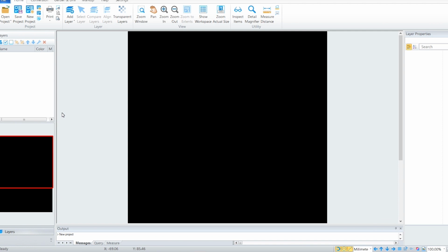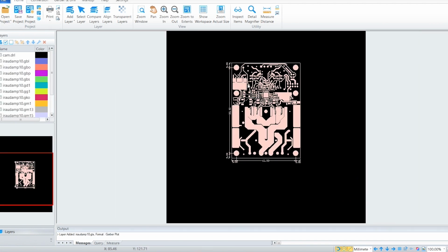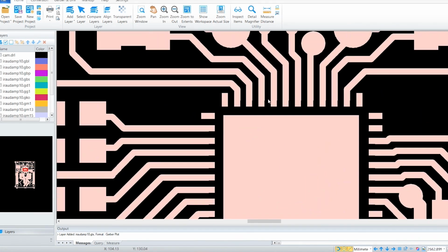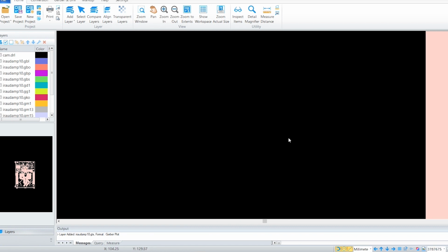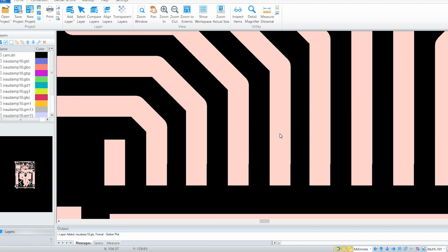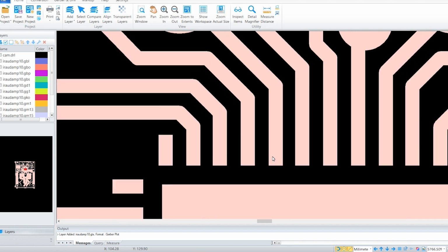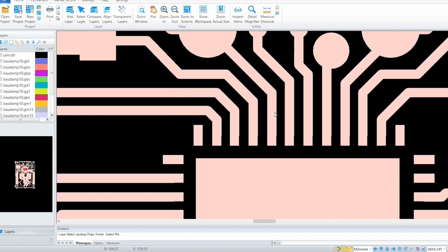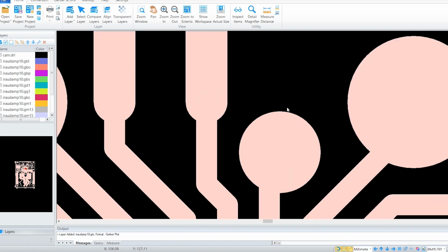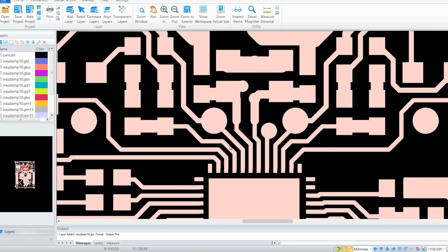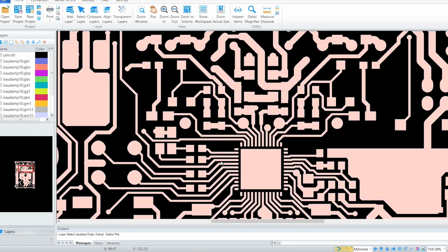How about the Gerber files? Here we have a Gerber file. And if you zoom in, perfect. I zoomed in, I don't know how deep I zoomed in. It's absolutely perfect artwork. And this is the artwork that we want to print. We don't want to print JPEG, PNG or TIFF files. We want